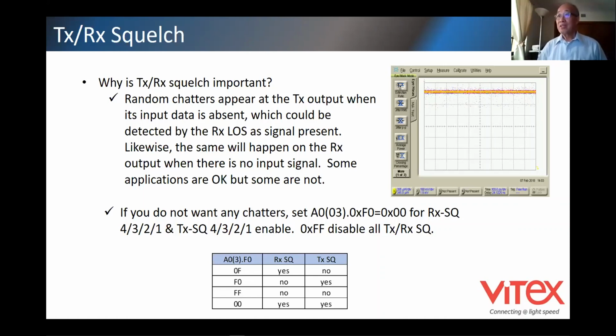They track receive amplitude, peak to peak, right? AC, we call it AC. So what happens if there is no data coming in, right? For instance, if the transmitter data is shut off, but the average optical power remains the same. If that happens, you would have a situation called chatter, right?